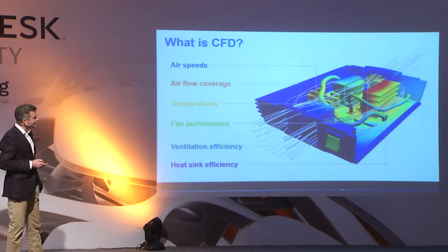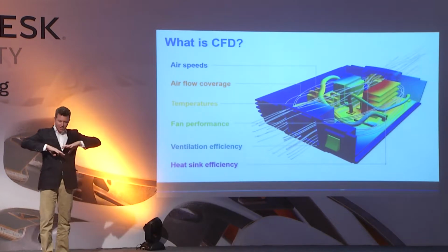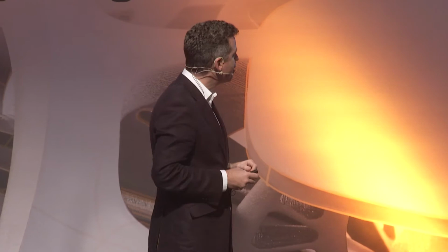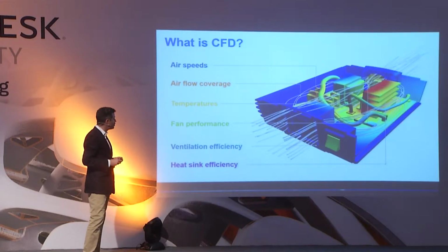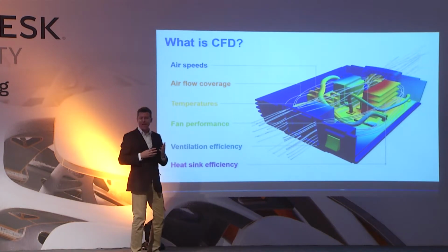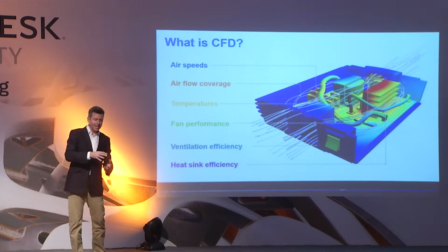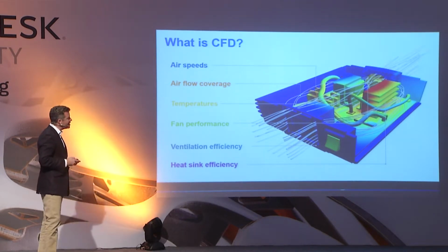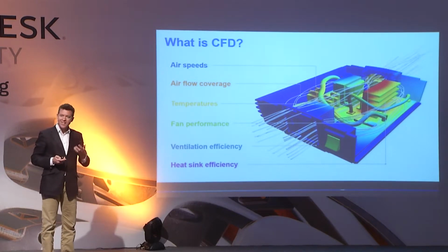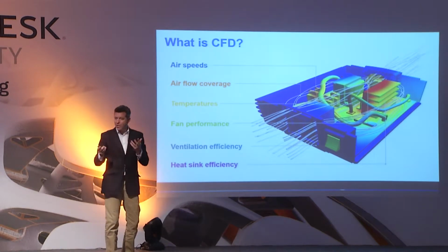So through the use of CFD, it's possible to visualize how the air moves, how the airflow covers a product, or how it's balanced inside a product. We can look at the temperatures, we can look at the performance of a fan, if we're including one, and we can look at the effect of different ventilation strategies, how efficient the airflow is at entering the products and leaving the products. And finally, if we're using heat sinks to remove heat, we can see how effective that heat sink is. Maybe the heat sink needs to be redesigned or relocated.